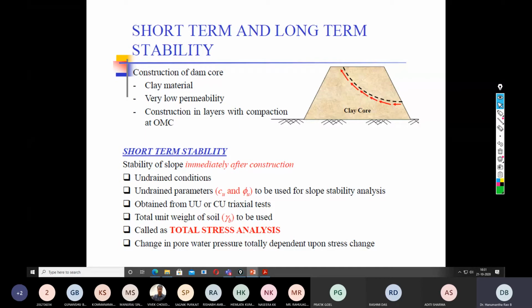And the UCS is mostly important for the transportation engineer, not for the geotechnical engineer. So as a geotechnical engineer, you always have to advise to conduct either UU or CU. So never ever encourage the shear strength determination by UCS. UCS is typically valid for transportation engineering, not for geotechnical.